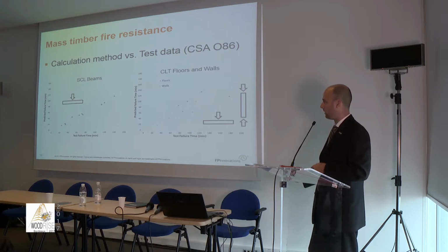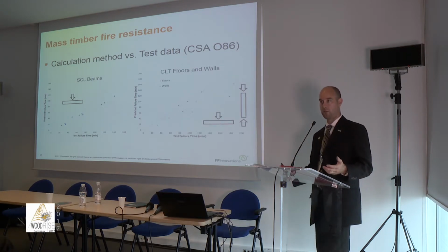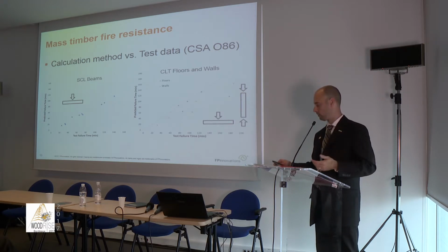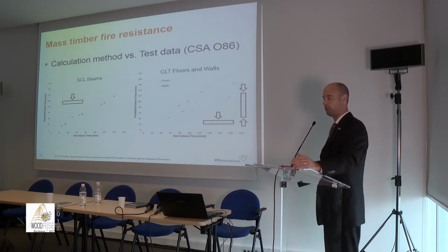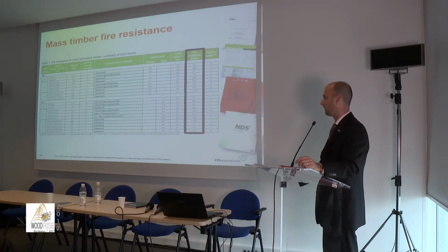There are also other test results on structural composite lumber and CLT floors and walls. And most importantly, what I'd like to highlight, especially on the CLT, is all the test results that are beyond 90 minutes. There are many test results available, not just in Canada, but plenty of other tests that show that 90 minutes and 2 hours can easily be achieved for fire resistance.